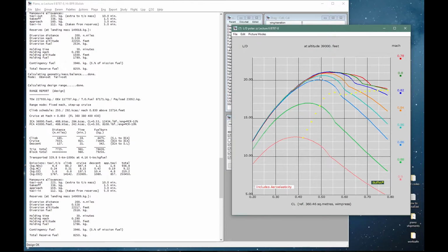Of course, there can be no complete certainties in several of our choices, and deciding these kind of adjustments assumes some knowledge of characteristics together with some trial and error. Accumulated experience becomes applicable to other similar aircraft in the database, and that is the nature of calibration in PIANO or in any tool. Let's now save our plane,